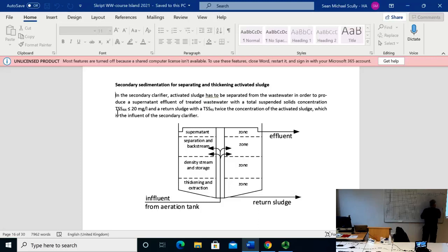Well, the sludge is actually separated in 2 streams. We might do this right away. This is our surplus sludge, which leaves the system. In the surplus sludge are all the microorganisms which grow in the biological stage. This is all what we consider the mechanical treatment, which we have treated so far. And this is the biological treatment.